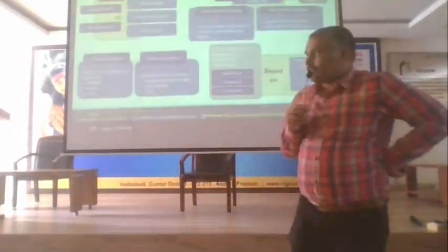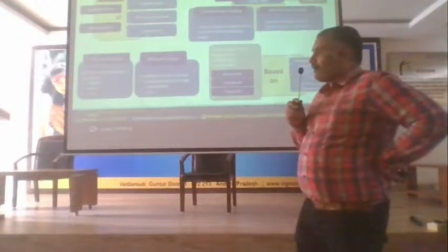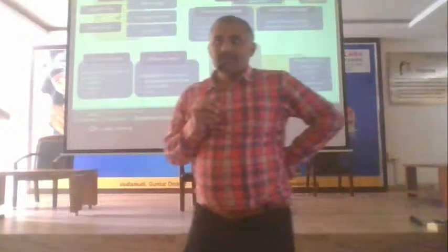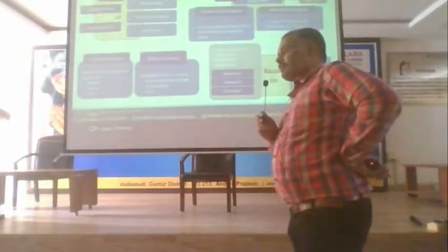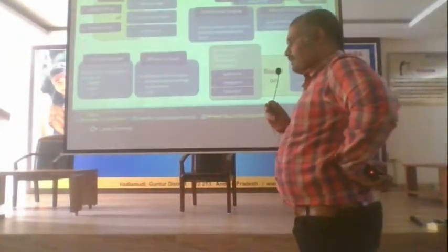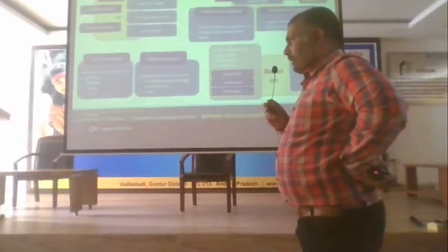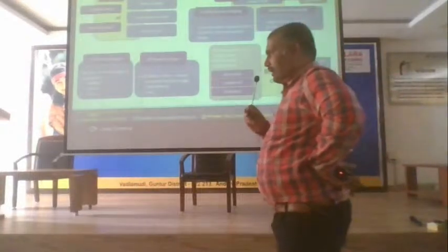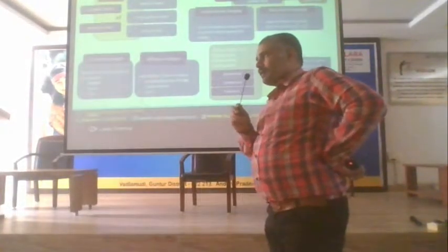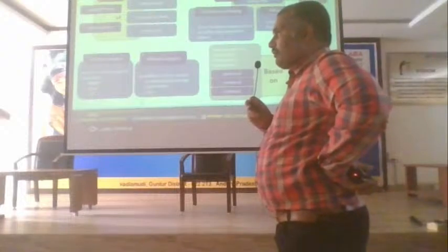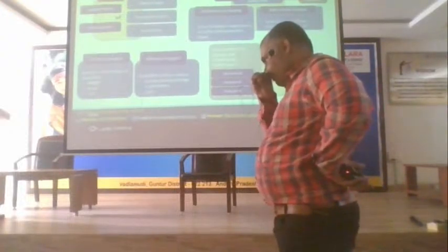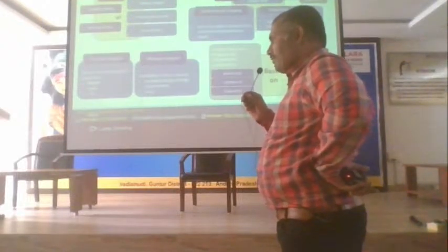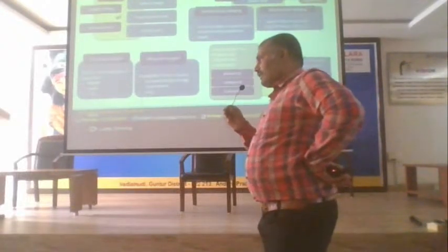Welcome back to our discussion. So far we have discussed how to make a BMS: once we have a model of some battery technology, how we can model the batteries, and how you can bring your real-time battery data to MATLAB. Then at the battery cell level, we monitored parameters like voltage, current, and temperature, and estimated SOC, SOH, and SOF.